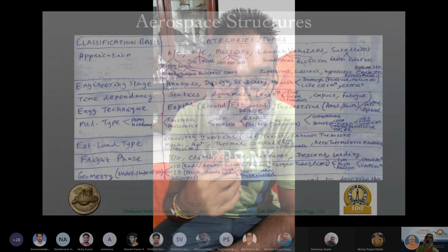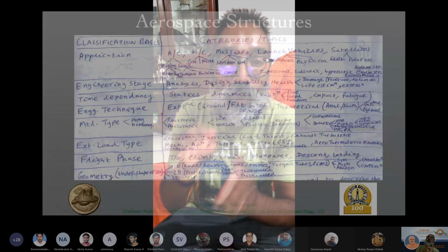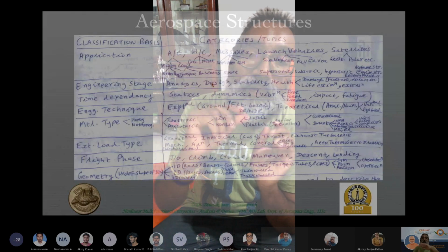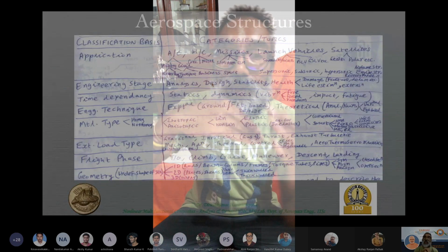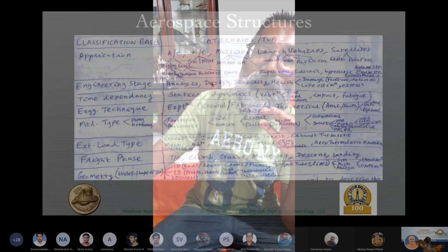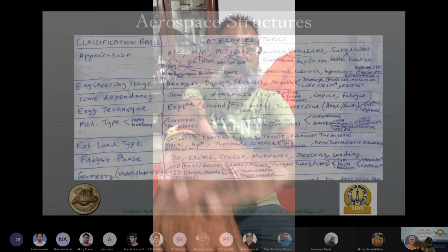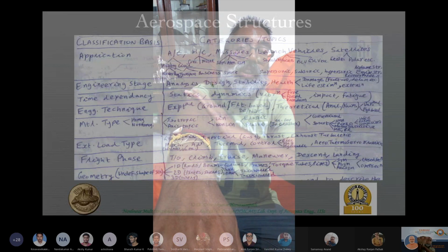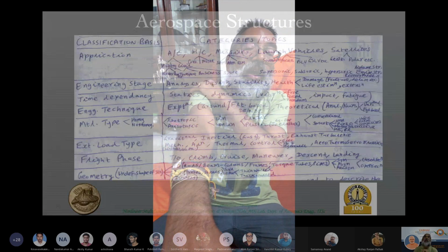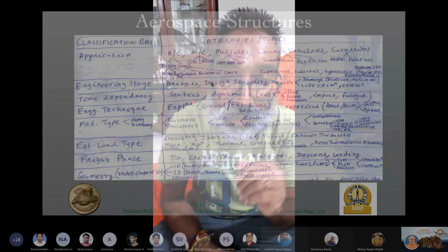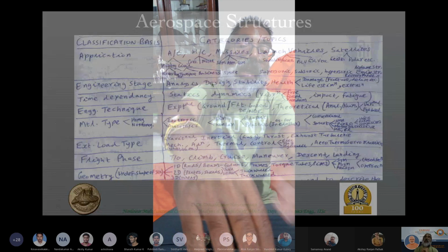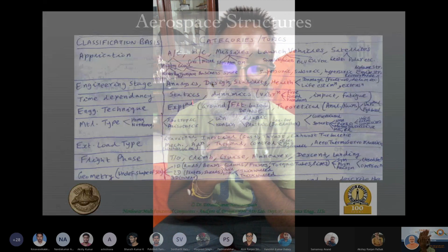The aerodynamicist might tell you the shape of the airfoil as a whole, so you know the outer shape of the structure of the wing, but then inside what goes into it, what is the thickness of the wing panels that you want to have on the top surface, on the bottom surface, how they are going to change along the length of the wing, because throughout this span you do not need to have that kind of a thickness, because the stresses are going to be much higher closer to the root where the wing is attached to the fuselage, and therefore at that location you might need a thicker configuration. So this kind of tapers down in terms of ply drops, etc. So how do you design that?